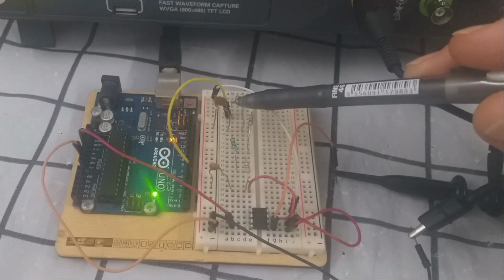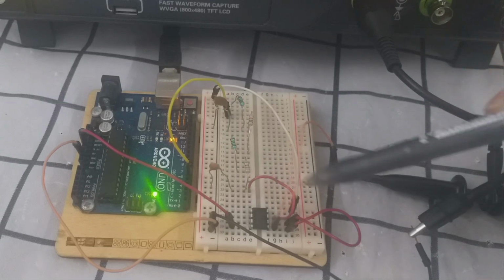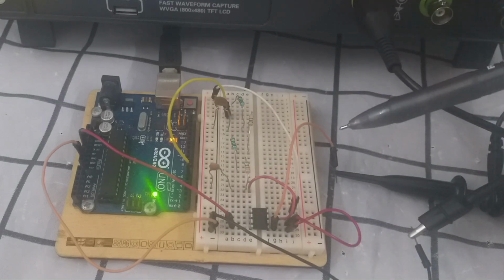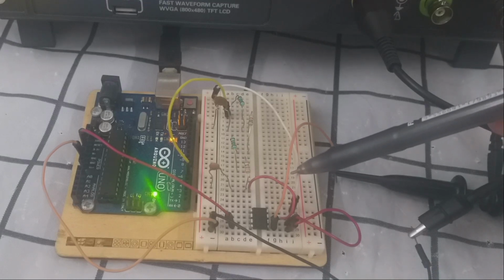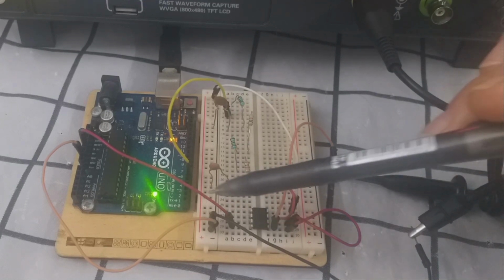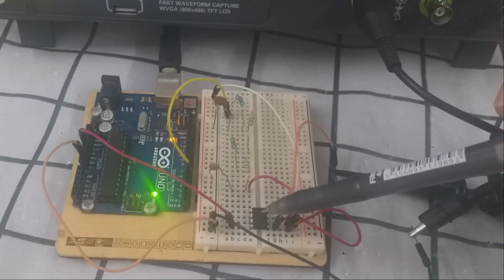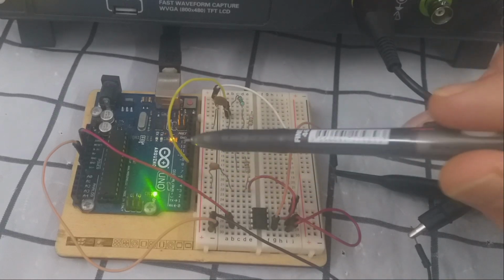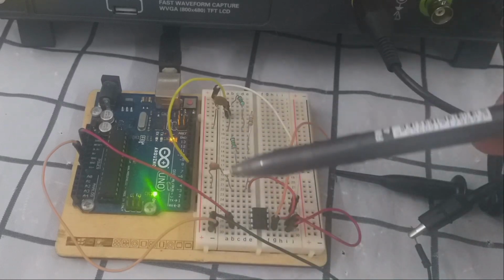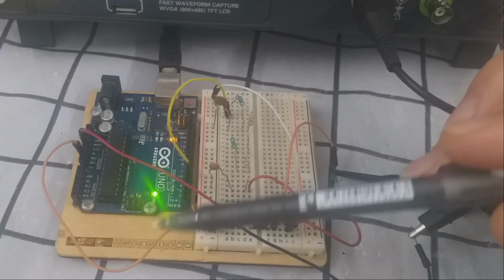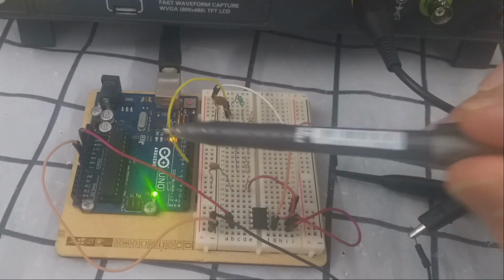I took it from here. This is the output of our first order, second order low pass filter, connected to pin number 3. Pin number 4 is the ground, I believe, and pin number 8 is our VCC connected to the 5 volts. But for sure, this shouldn't be connected to the same source as the Arduino, because the Arduino will not supply that much current. It should be an external source or connected directly to the power supply of the circuit. But just for the sake of demonstration, I connected it to the VCC of the Arduino.